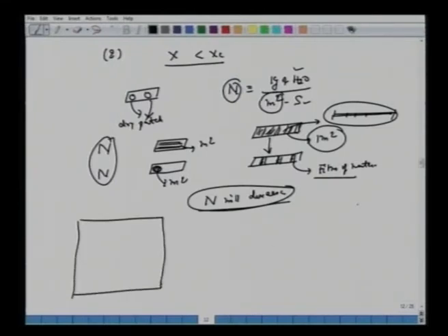So if you do this experiment, you suspend the solid and measure how the moisture content decreases. Then you will expect that here also you will have several regions. There will be one region where X will decrease linearly, then it will slow down, then it will further slow down. So next time when we meet, we will mark these points A, B, C, D here.